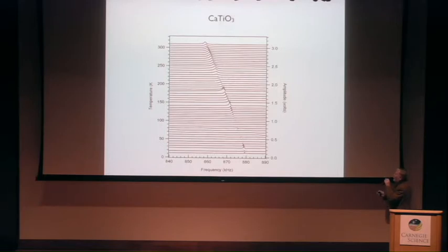So you can see in calcium titanate, the polarity and the piezoelectricity is only in the domain walls. There's absolutely nothing in the bulk. And you can see these few domain walls alone, when you put an electric field in, they start to wiggle. And that's enough to produce a reasonably loud acoustic noise. And so if your microphone is good enough, and you can buy these things. I mean, we're not building them. You buy them, and they're quite commercial, good machines. You amplify it for a while, and then you find these resonance curves, even though the functionality is only in the domain wall.